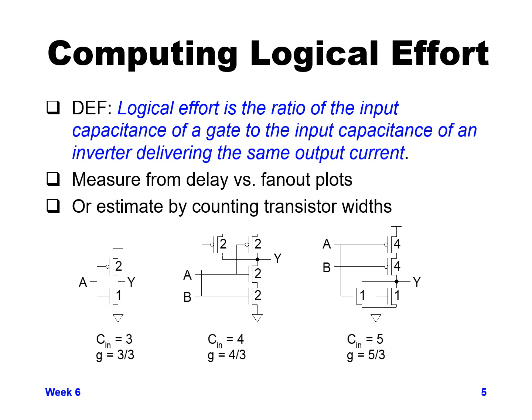Your PMOS devices are now in series with each other, which means they need to double in size so that the equivalent resistance between VDD and your output stays the same as a single PMOS would have been. So you need twice as wide of a PMOS because there's two in series with each other in order to keep the output current drive the same. So our PMOS is now size 4, NMOS size 1.